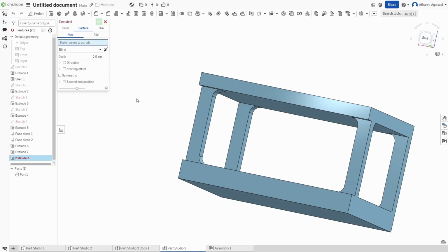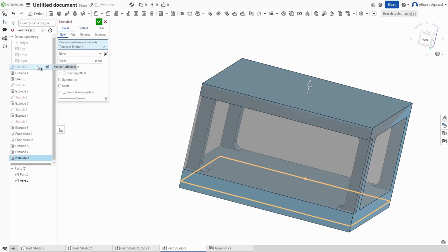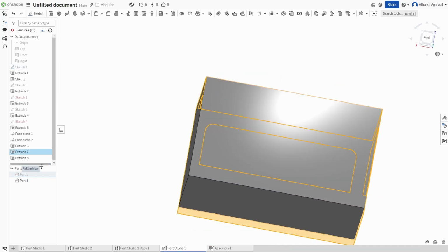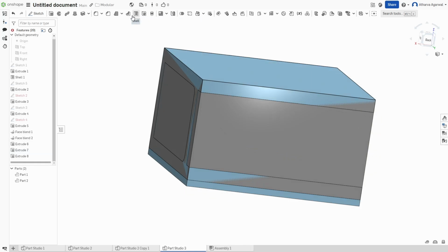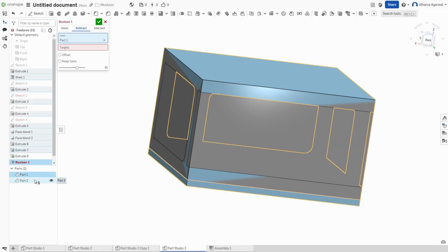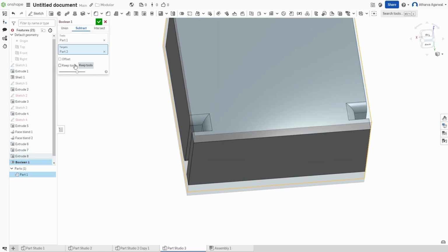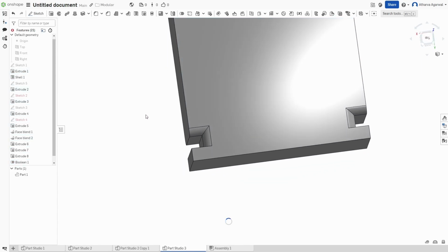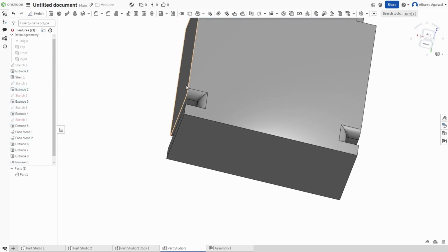So you can see me create a new extrude, change it to solid, and then select the sketch for original sketch 1 for the extrusion base. Because the software automatically gave it a different color of gray, I purposefully left out increasing the gray by 0.5 at the bottom. This was because it was unnecessary and I'm only trying to create the container, and that ought to be removed already. So now I go boolean subtract, and for my tool I would click part 1 and my target is part 2. Basically your tool is what is being removed and your target is the shape which you're removing from.